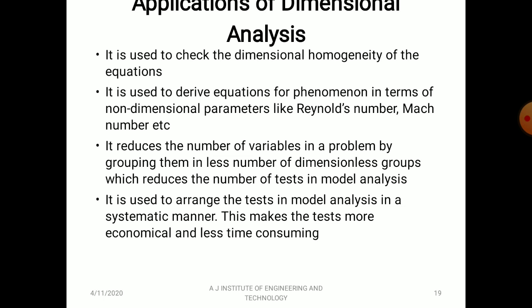It reduces the number of variables in a problem by grouping them into a smaller number of dimensionless groups, which reduces the number of tests in model analysis. So by using dimensional analysis, you can group the variables into dimensionless terms. That reduces the number of tests in model analysis that may be related to prototype analysis.